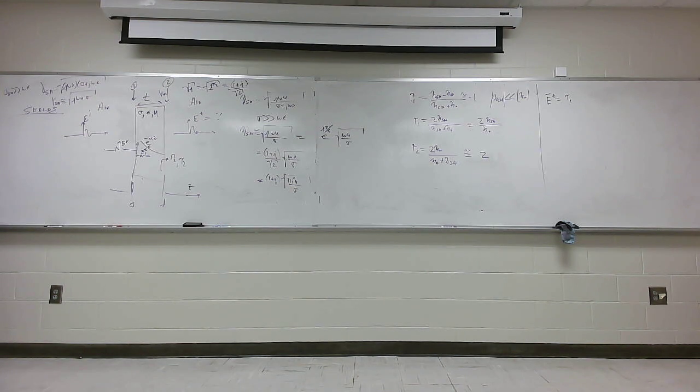Well then, I'll put it right here. Gamma of the shield is equal to the square root of j omega mu sigma. The square root of j is 1 plus j over the square root of 2, times the square root of omega mu sigma, right? And that means it's what, really? It's the square root, omega is 2 pi f, so it's the square root of pi f mu sigma times 1 plus j.